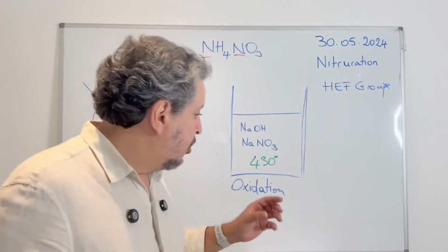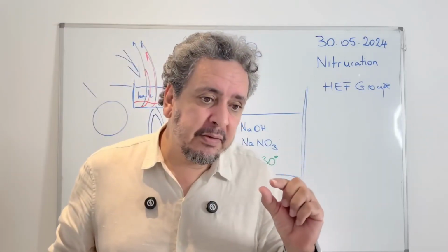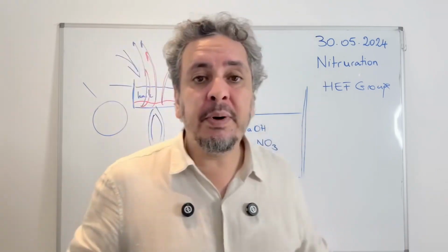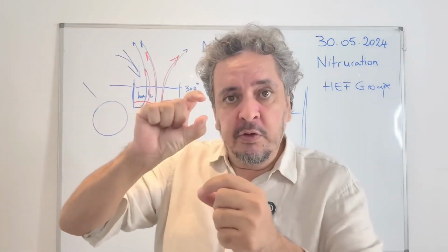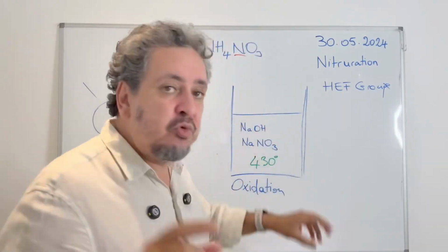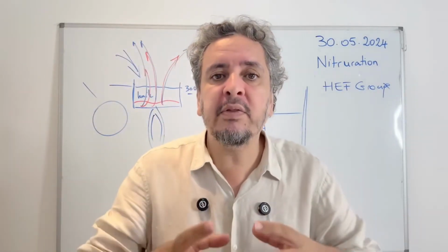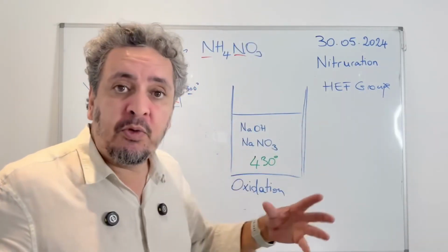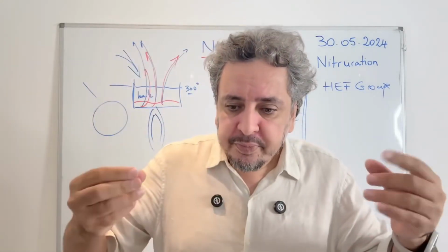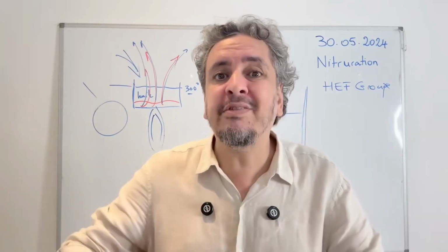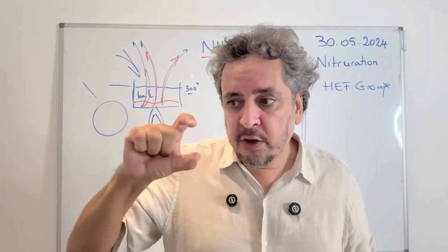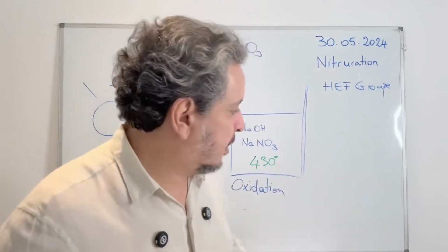Actually, what happened is that when we look at one of the 5 mm holes, when we took it out from here, we put it in the water bath. What happened is that the salt created a blockage. Because the salts, when they cool down, they harden. Right now they're liquid because they're at a high temperature, but once they cool down, they will harden. So the salts created a blockage, so they closed up that hole.